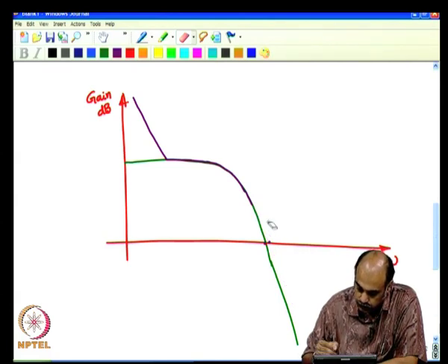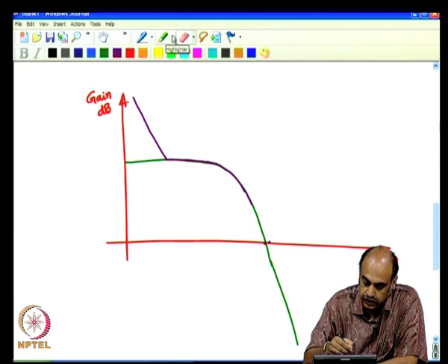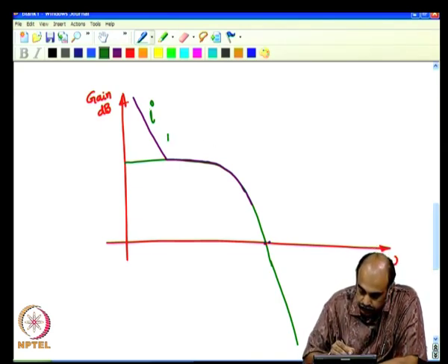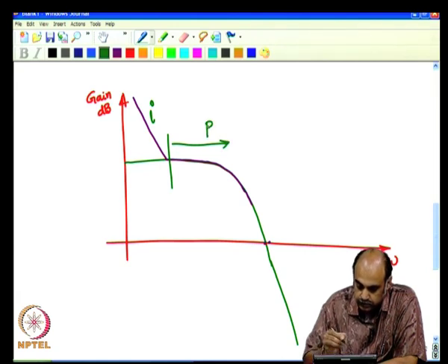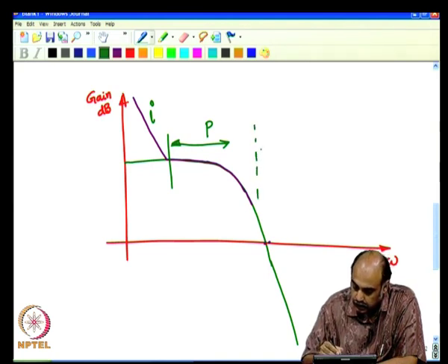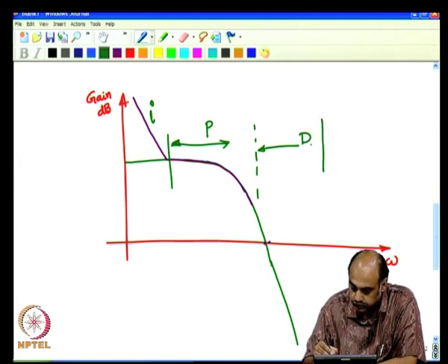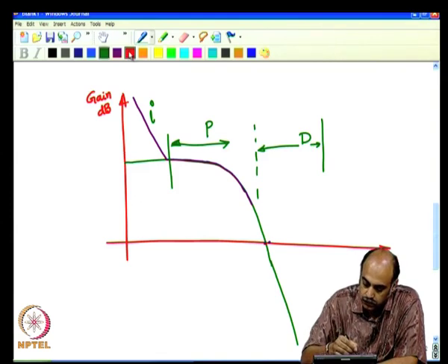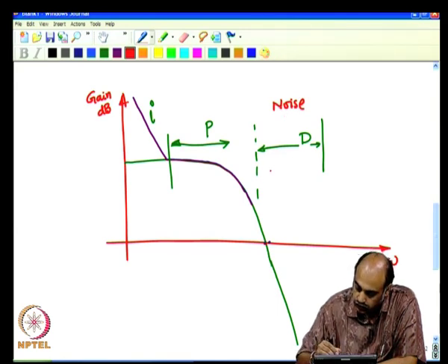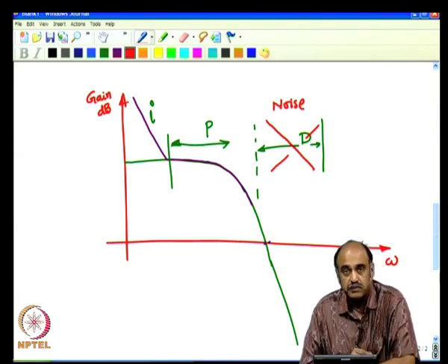just to have the proportional and the integrator portion, the I, and after some point the P, proportional portion. After some point, actually that is where the D portion comes in, because these are noise sensitive zones. It is always good to avoid the D in the first iteration.